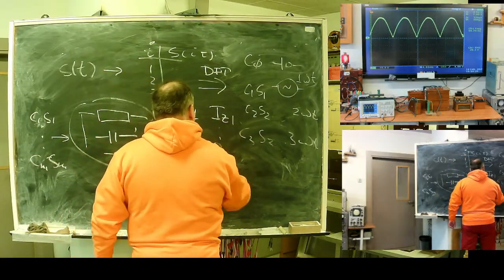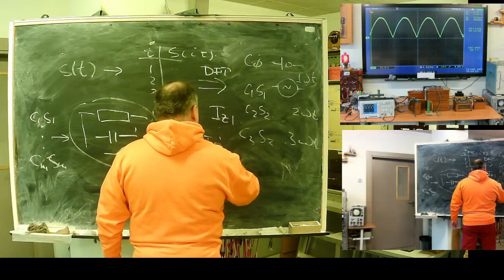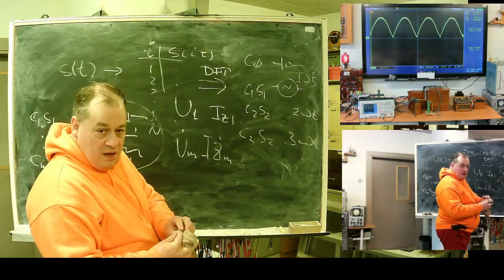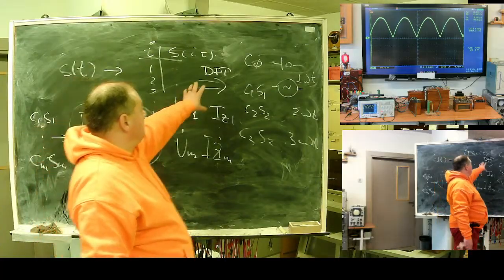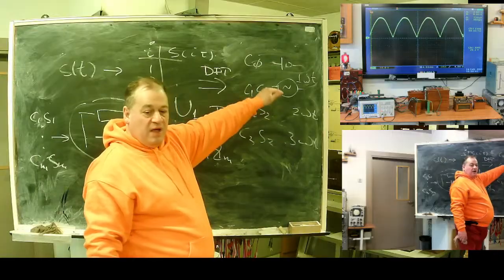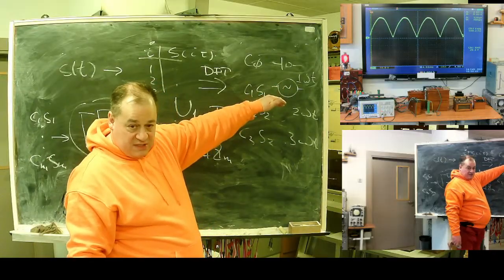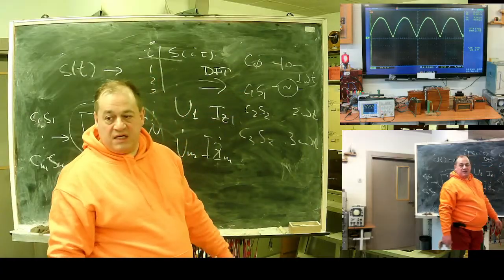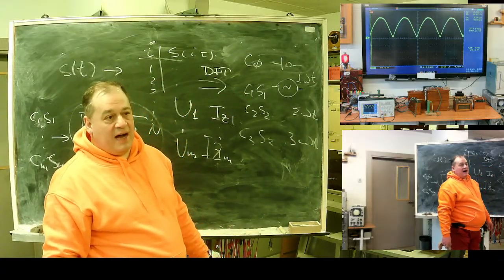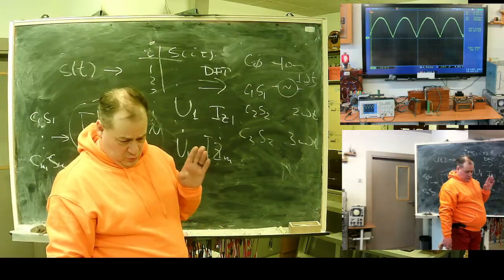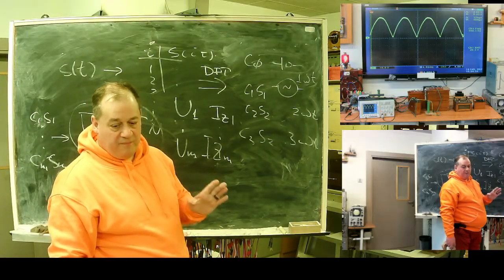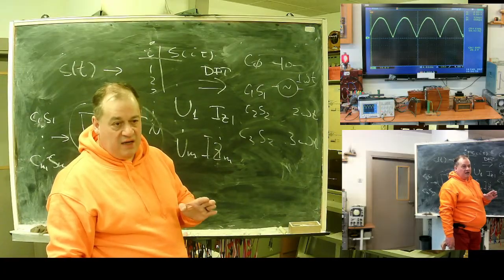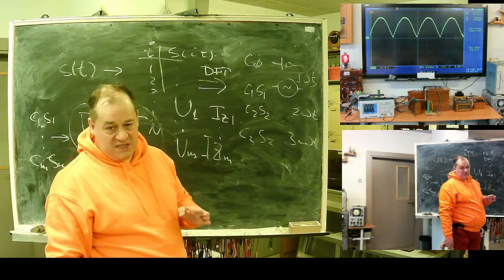I will have a set of branch currents for each frequency. After the discrete time Fourier transform, I have a range of frequencies, starting from the base and ending at the Nyquist frequency. There is one law in all discrete transforms: the sampling frequency should be at least twice higher than the maximum frequency of my signal.